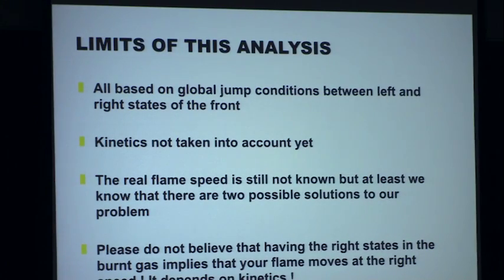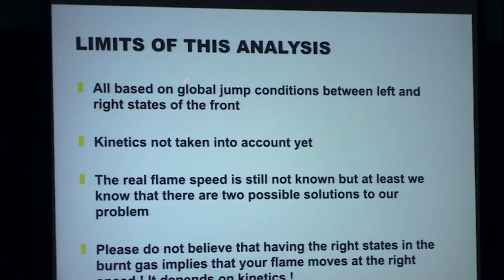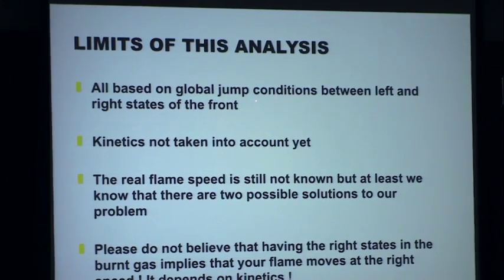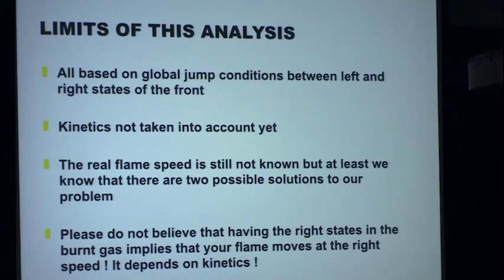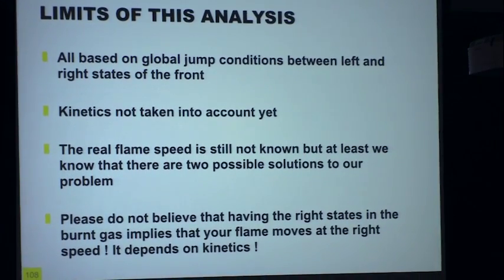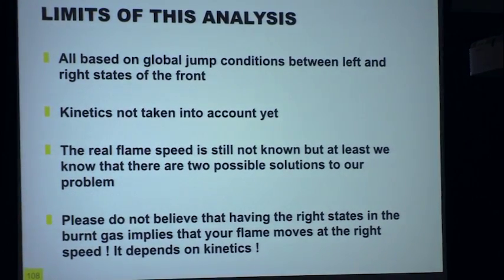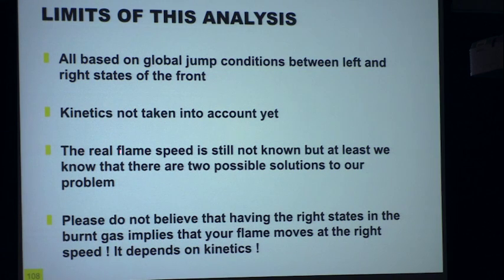Just a word here about the limits of this kind of analysis. Everything I've shown you is just possible jump conditions between two states, burnt and unburnt. I'm not able to talk about the speed which will really be reached between these two states. That depends on kinetics, and Paul will talk about that tomorrow. But still, it's important to know that there are two possible solutions to this problem, and they are very different. So you need to include kinetics, and Paul will talk about it tomorrow.